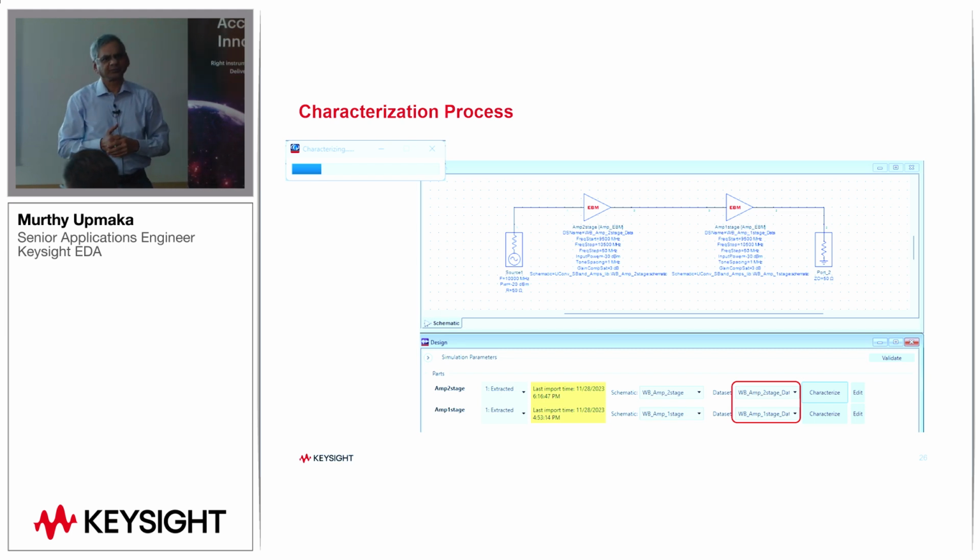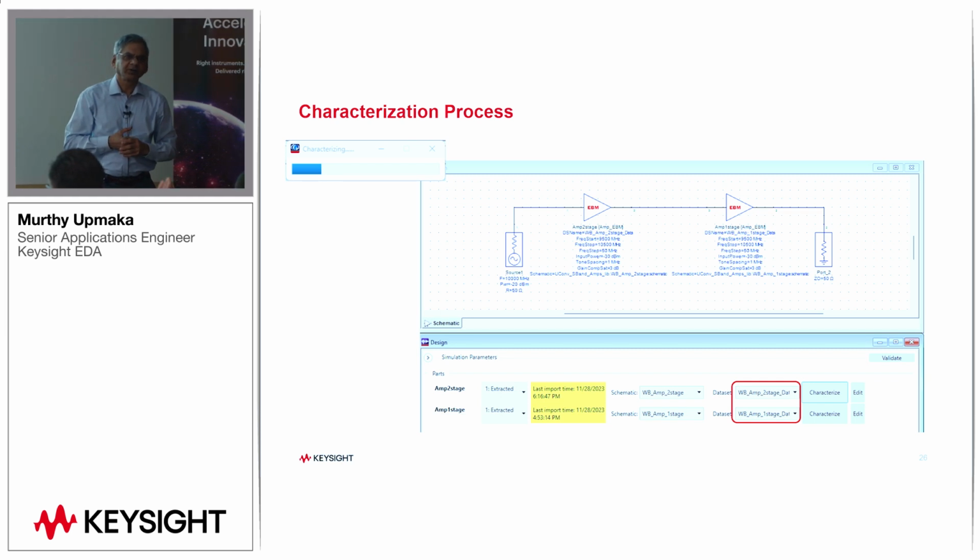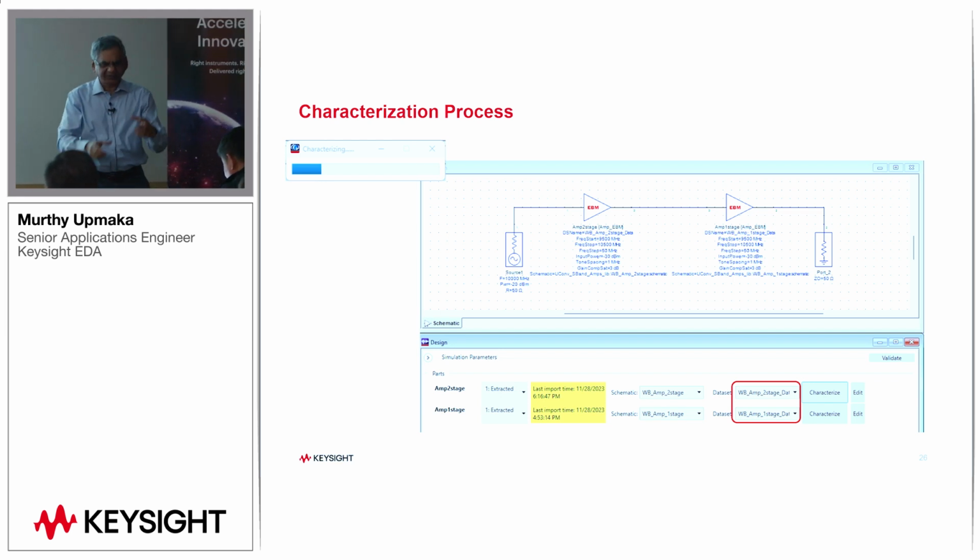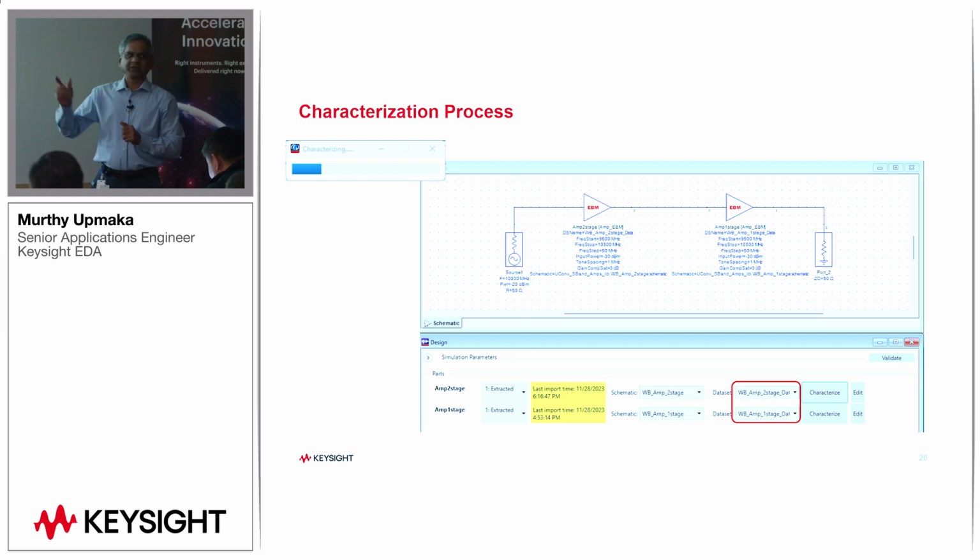Yes? You just said something. So the S parameter set that this is built on changes after drive level, so there's multiple copies of gain. Is gain compression represented by another table of S parameters? No, it runs the power sweeps, and then from the compression curve, it derives the IP3. Oh yeah, it does automatically all those things. We don't have to do anything. It just does everything. It's almost like putting a network device to a network analyzer and pushing the button. That's what you're trying to do here, except that you're doing it in ADS.